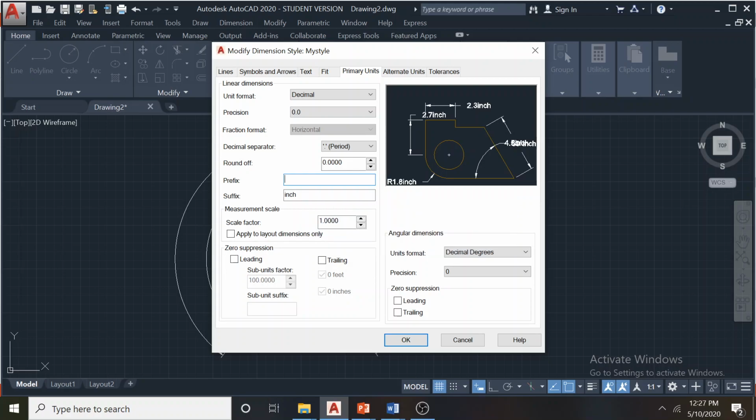If I want to place a diameter symbol as a prefix, you can have it, but the problem is here also diameter, here also diameter, here also diameter. So this is not very good. In some drawings, say you want to type the English word radius, but everywhere it comes as radius, so we have to avoid this in other places. I will discuss later how to avoid these other places and have a prefix. So the prefix can be customized, no problem.